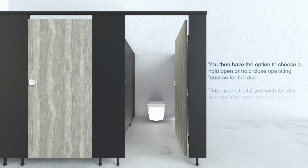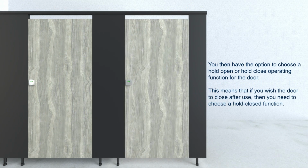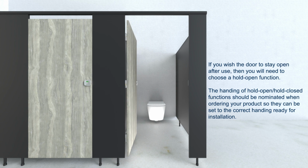You then have the option to choose a hold open or hold close operating function for the door. This means that if you wish the door to close after use, then you need to choose a hold closed function. If you wish the door to stay open after use, then you'll need to choose a hold open function. The handing of hold open or hold closed function should be nominated when ordering your product, so they can be set to the correct handing, ready for installation.